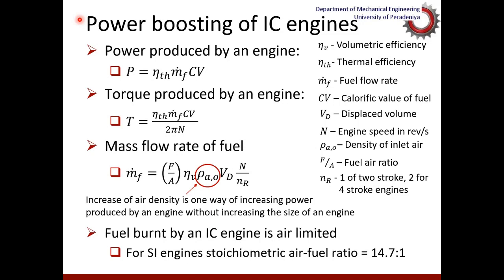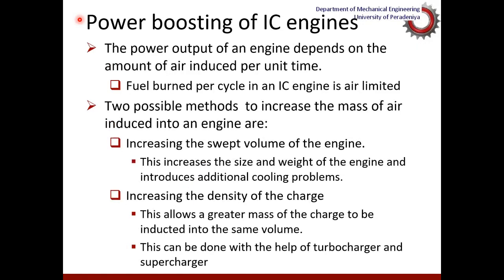And accordingly, we can see, as we understood earlier also, the fuel burned by an IC engine is limited by the amount of air that you sucked into the system during the intake stroke. So usually the air-fuel ratio in gasoline engines is more or less fixed at stoichiometric. So the more air you suck in, the more fuel can be burnt and the more power can be produced. So in order to boost the power produced by an engine, we could think of two possible ways, as I just mentioned.